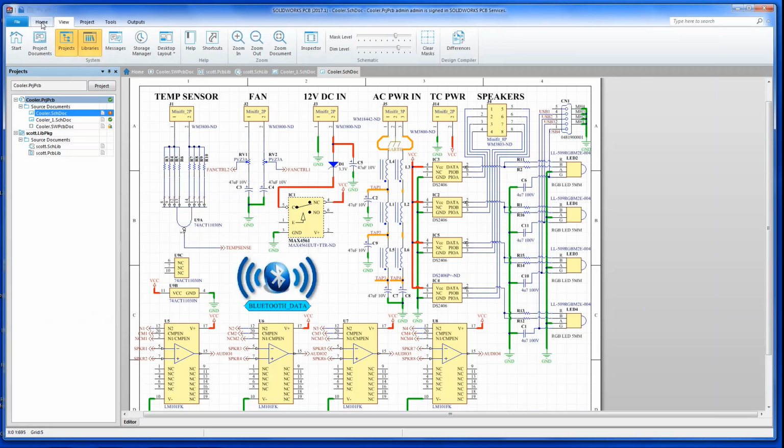So again, I mentioned the functionality of the tool being quite simple. It's project driven, so the schematic capture documents and the PCB documents are contained within the project within the single application. So in those instances where you have multiple engineers, some companies have individuals that do just exclusive circuit design, schematic capture. Others are dedicated exclusively to doing circuit board layout. These tools can pass files back and forth very, very easily.